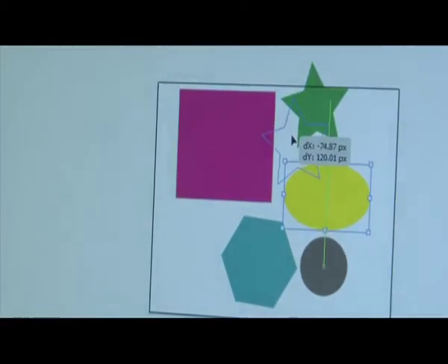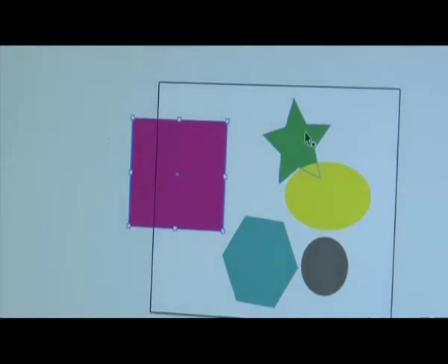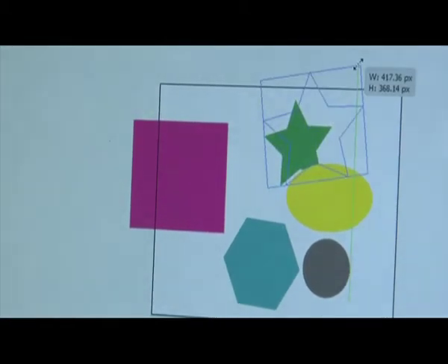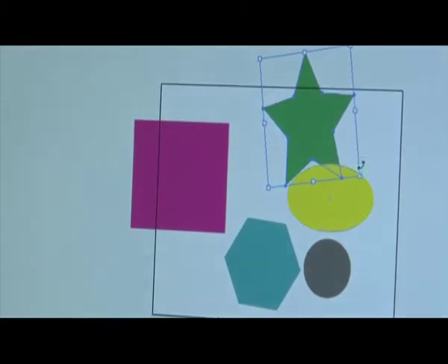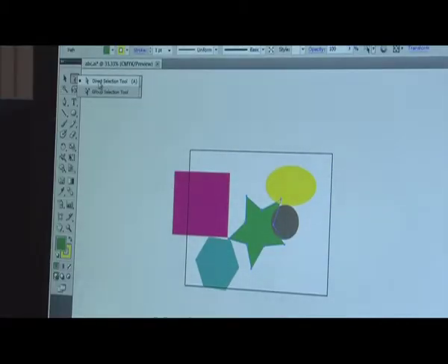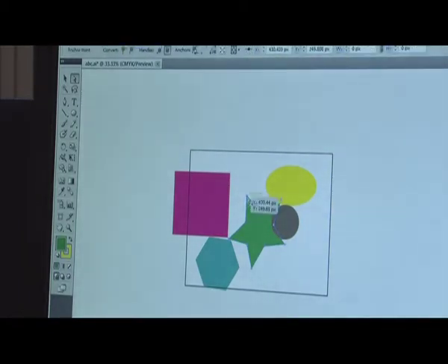Selection tools. There are 2 types of selection tools in Illustrator used for selecting objects. The Selection tool is used for selecting and moving a shape. It can also be used to resize a shape. The Direct Selection tool selects a single anchor point instead of the whole shape, used for editing an anchor point of a shape. Click once on a point to select and hold Shift to select multiple anchor points.